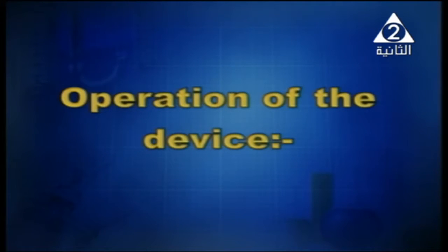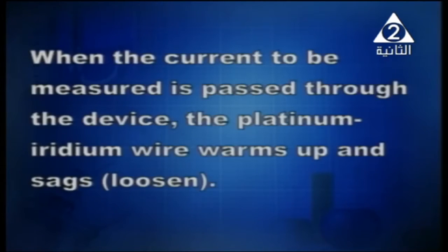And what about the operation of the device? Let me remind you something. It is based on thermal effect of the current. And now talking about operation of the device, its mode of work. When the current to be measured is passed through the device, the platinum iridium warms up. An amount of heat is generated and it expands, so it sags.